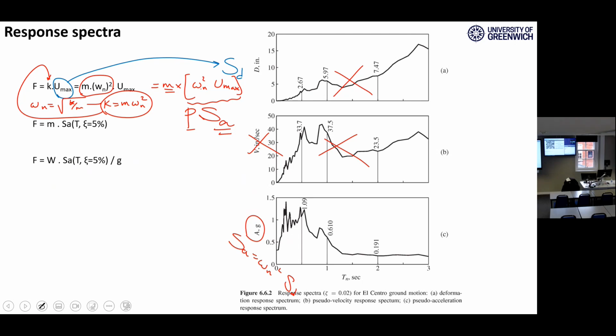Stiffness is a little bit tricky. I need to calculate the stiffness. It depends on the support conditions, on the connection of beam to columns, and many other things, right? It is not very difficult, but there are some big uncertainties in calculating the stiffness values, for some reasons. But the mass is very clear.